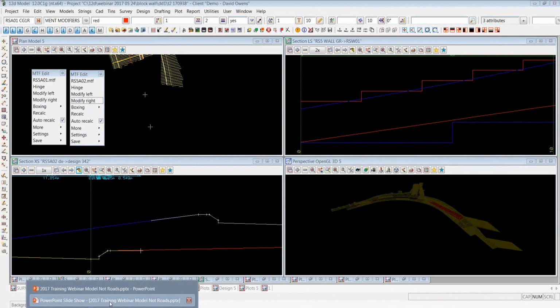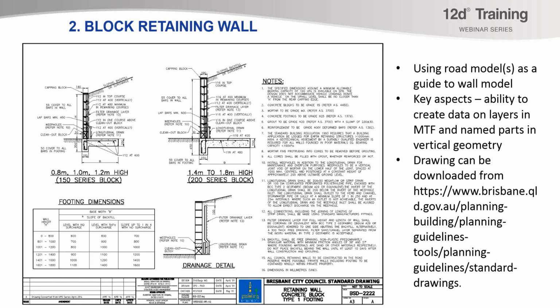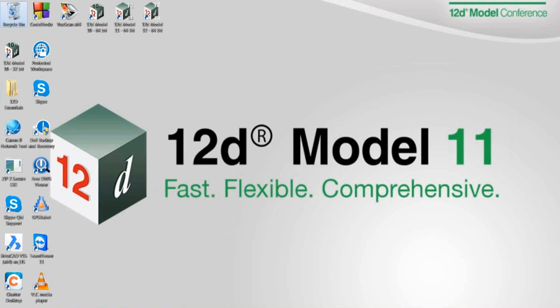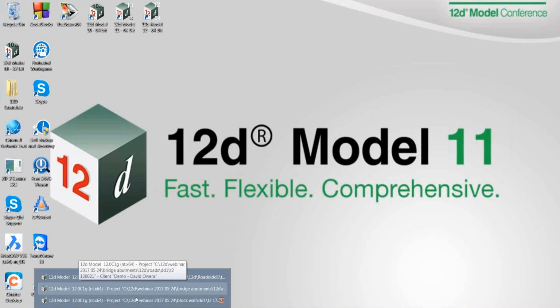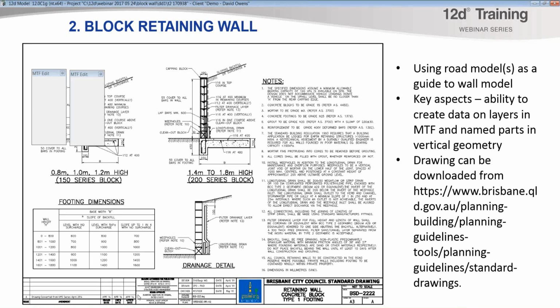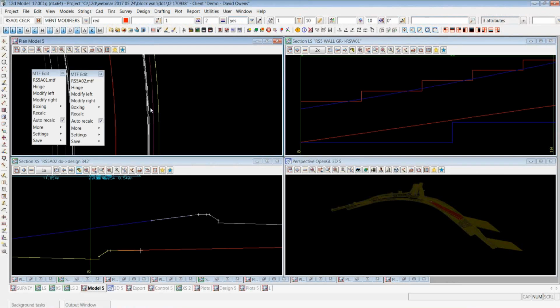You can see, I don't know if you can see there, but there is just a little 30mm offset between the footing and the actual wall itself. So that's how I've done them horizontally. There's two alignments running through the middle of this median here. It's extremely tight, but there are two alignments in there.